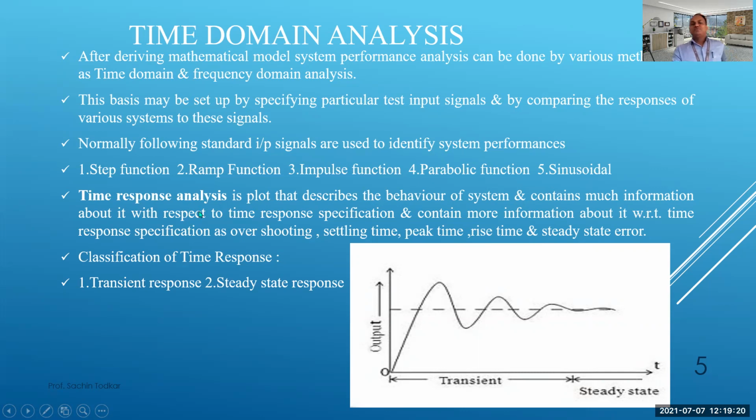Now, what is time response analysis? Time response analysis is the plot that describes the behavior of the system and contains much information about it with respect to time response specifications such as overshoot, settling time, peak time, rise time, and steady state error. All these terminologies are very important. We are going to see in the next slides their definitions and how they have been derived. Now, classification of time response.